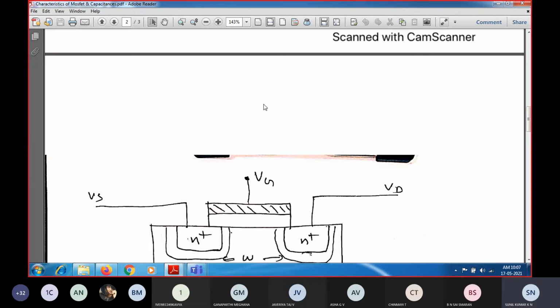Okay, so the internal MOSFET capacitance will usually be inactive in the low frequency operation of the signal. Those internal MOSFET capacitances will start conducting when it is going to operate at a higher frequency. So whenever we discuss the high frequency model, we are going to consider the capacitance effect. At high frequency, these internal MOSFET capacitances will cause the gain to roll off.